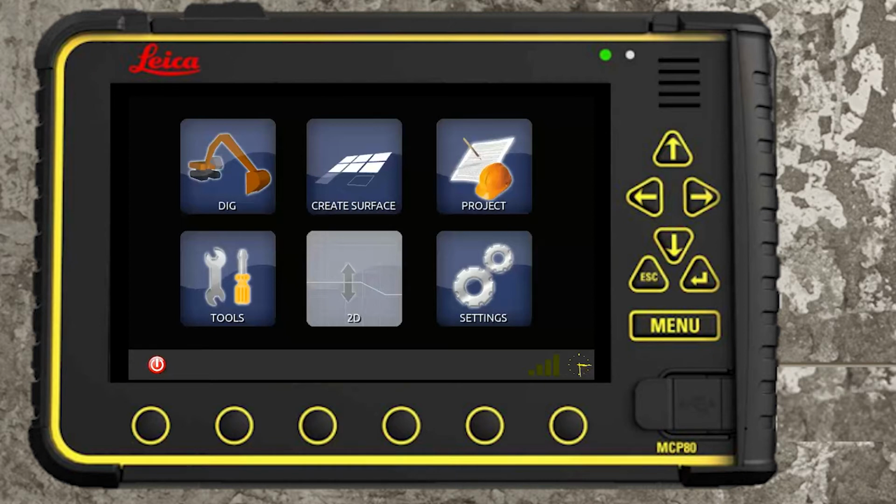Two things with the avoidance zones. The format of the file has to be a .geo, and the file itself has to be a closed polygon. Okay, that's two important things to remember: it has to be a closed polygon and it has to be a geo file.